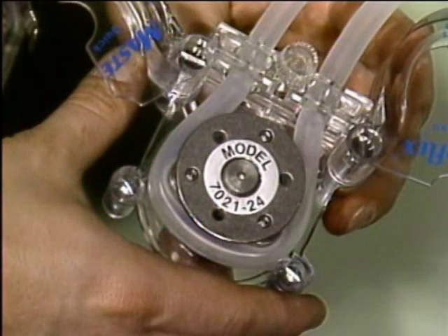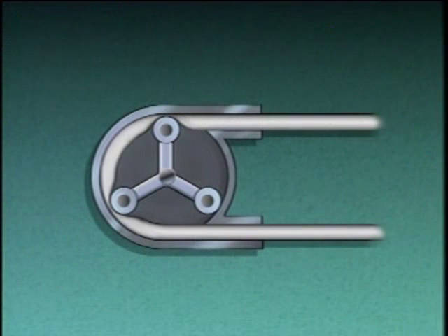In some pumping applications, it's critical to keep the process liquid away from the pump's moving parts. One type of rotary pump that can be used in these applications is a tubing pump. In a tubing pump, the process liquid is contained inside a flexible tube that's part of the pump. The pump's rotor works with the tubing to force the liquid through the pump. We can get a better idea of how this type of pump works by using this illustration.